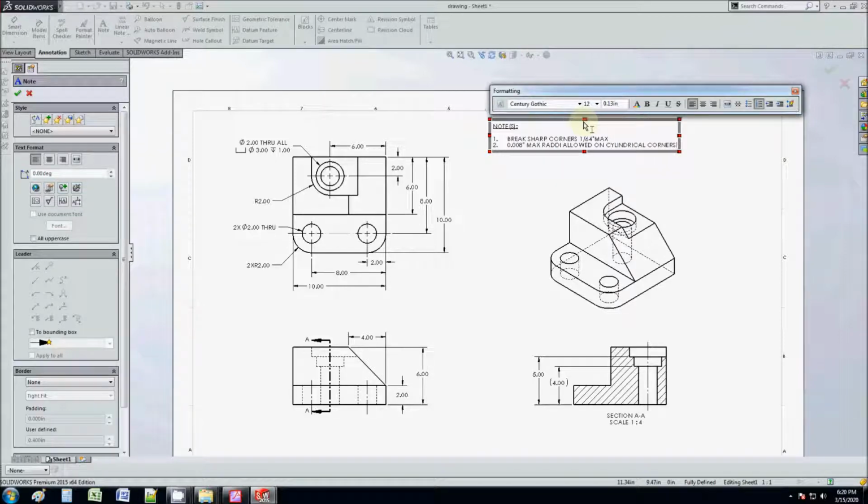It doesn't apply to this model, but when you have a cylindrical object, it's good to give an allowance on the corners to say, hey, I don't really need it to be a sharp corner. Because of the lathe insert radius, you can say it's okay if it's 8 thousandths or larger on that corner.